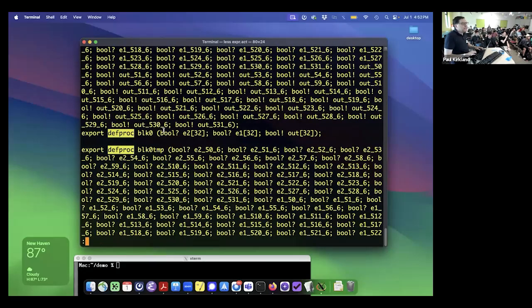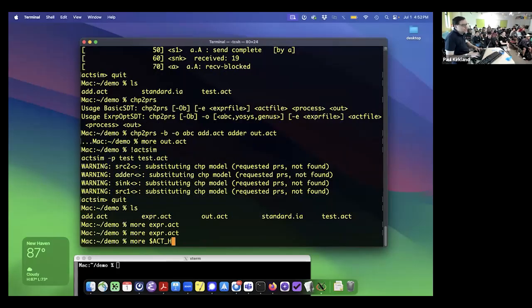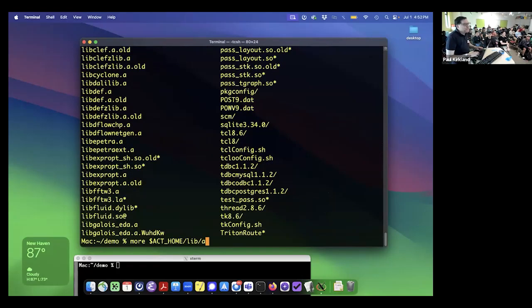So the block I'm going to connect to is this one. This little wrapper we have is for ABC; I can get into why we need it for ABC. We don't need it for Yosys or Genus. Block 0 has two inputs, which are 32-bit Boolean variables. That's standard combinational logic and a 32-bit output. So you can do synthesis from here with any tool, commercial or non-commercial. Currently we can do Genus, Yosys, ABC. By the way, the software engineering piece of this is something I'm quite proud of. I'll talk your ear off if you let me.